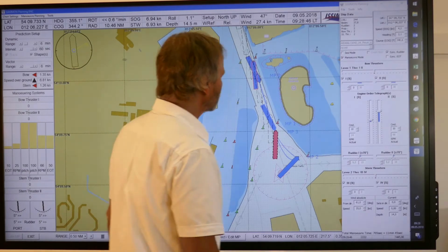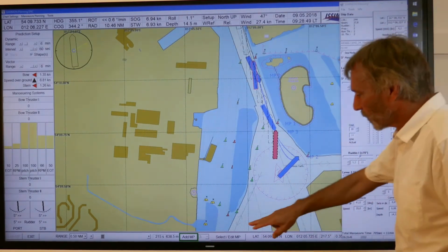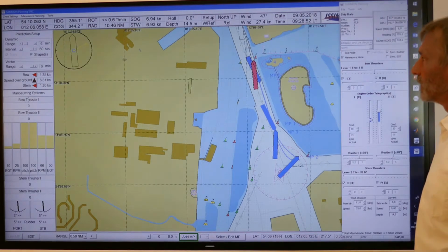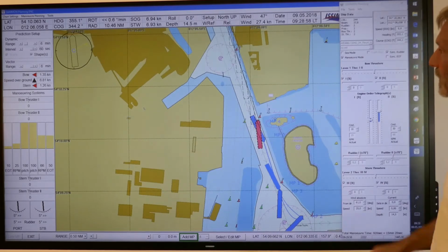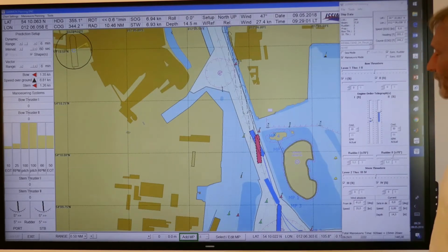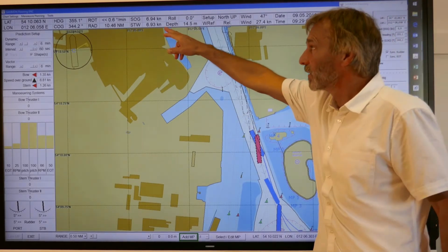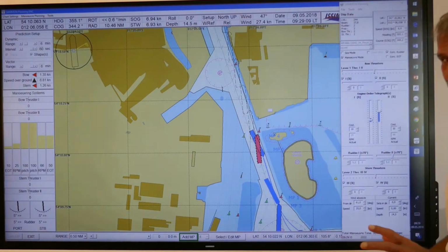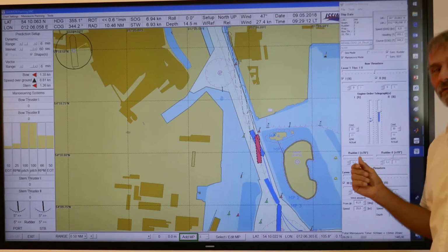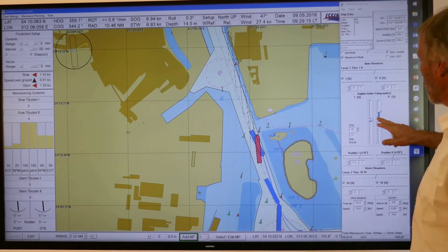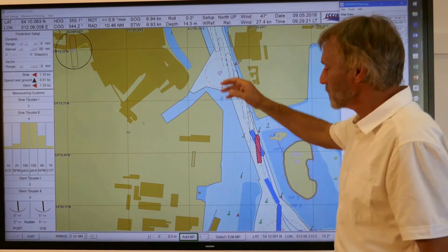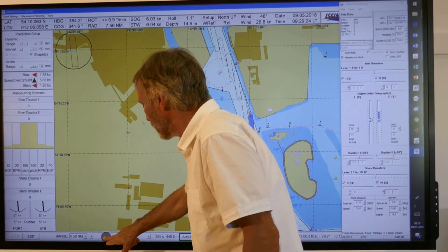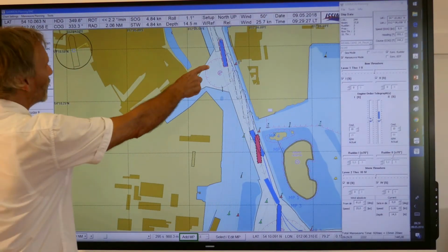So this could be maybe the next position for a maneuvering point, where we now go into the final part to stop her, and so we have to decrease. We have now 6 knots, nearly 7, which is not good for this channel. Normally it's allowed only 6.5 knots. But if we reduce now the engine, then you see, okay, we are just closing into the berth, and the remaining speed here would be only 5 knots.